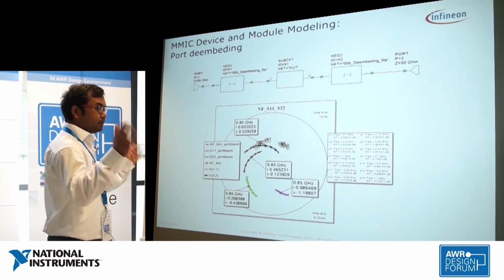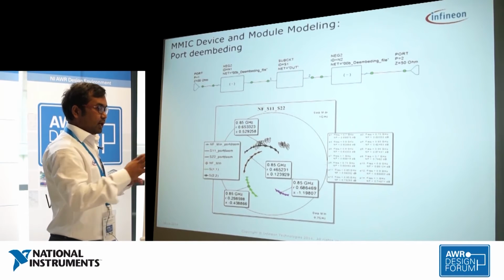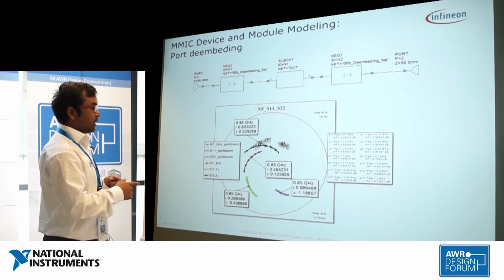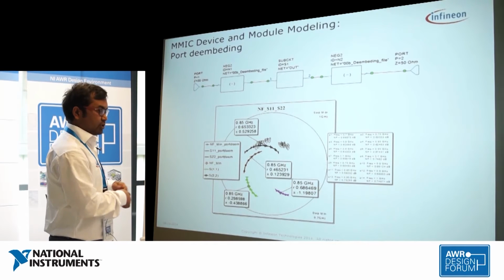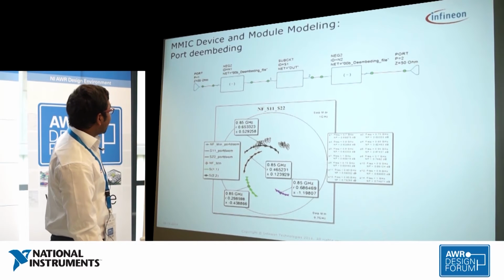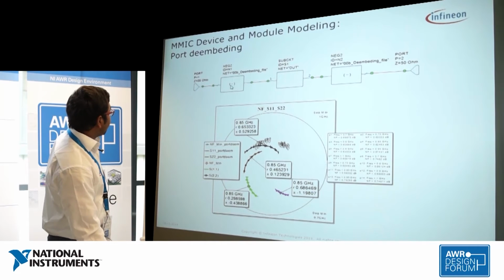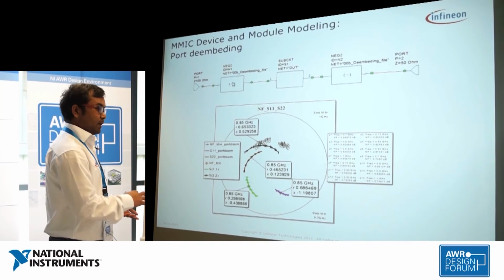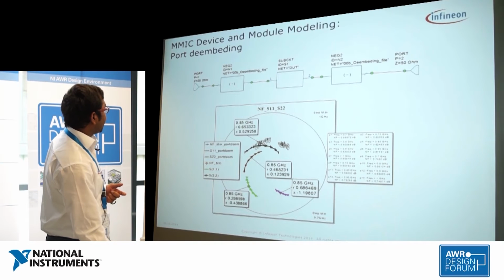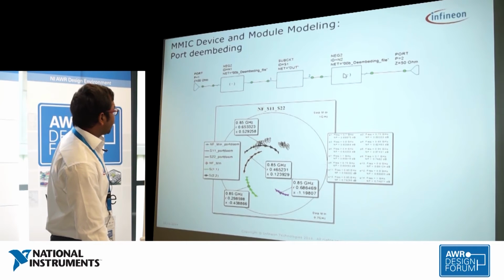We have the measurement results with input transmission line and output transmission line. To get the data only for the device, we need to subtract the input transmission line and output transmission line, and we use this neg block to subtract them. Inside this block we have the model of the input transmission line, and on the left and right side we have the output side transmission line.